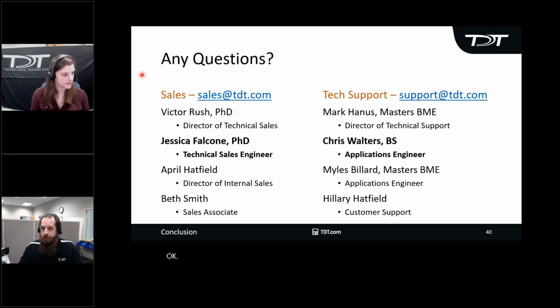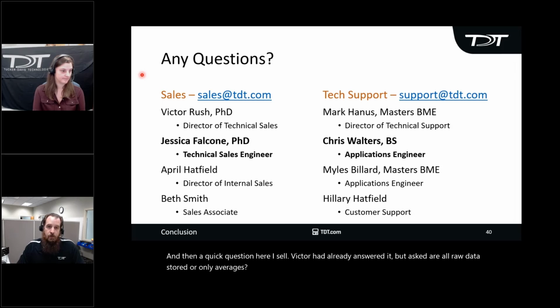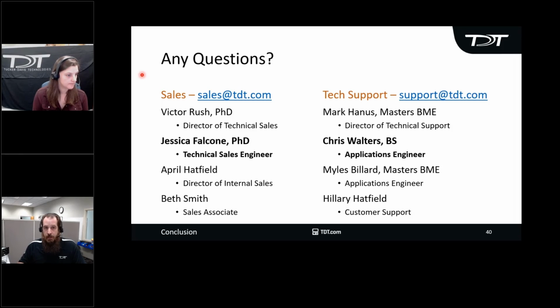And then a quick question here. I saw Victor had already answered it, but they asked, are all raw data stored or only averages? That's up to the user. With our current software that is available for download on our website, if you haven't updated recently, you can get access to this functionality if you'd like it. Traditionally, BioSig has given a number of averages, let's say 512 typically, but you can adjust that, and then it would give one averaged response. In the last version that we released, we let you save individual traces. So in addition to that averaged response, you also get each of the responses that comprise that average.